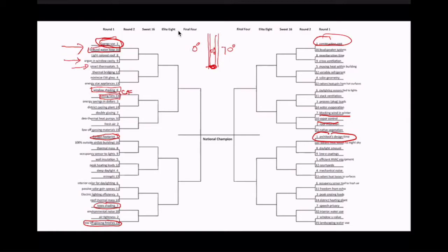So is the low-E film always on the second surface inside? It's always on the second or the third. They work approximately comparably well. I think one of them works ever so slightly better than the other, but it can be on the second or the third. So it's on one of the two interior surfaces, and it almost doesn't matter which one. Although I can't remember which one it's better for, summer, winter, inside or outside. But just know it needs to be in. So it's this one, the third one coming from outside. Yep. Okay.